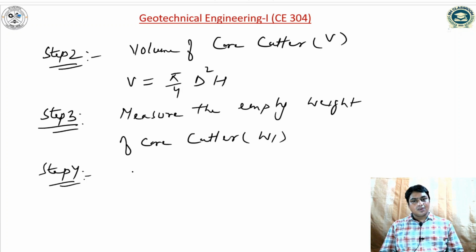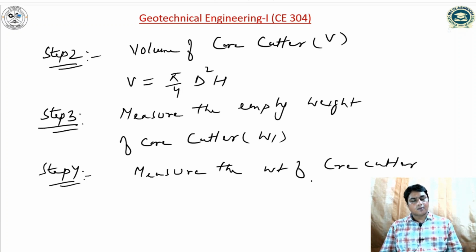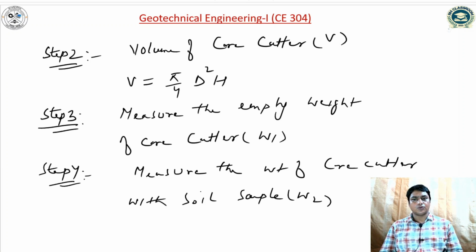with the help of any excavation tool remove the surrounding soil and extract the core cutter, and with the help of a knife plane the top and bottom surface of the core and once again weigh it. So measure the weight of core cutter with soil sample, say it is W2.